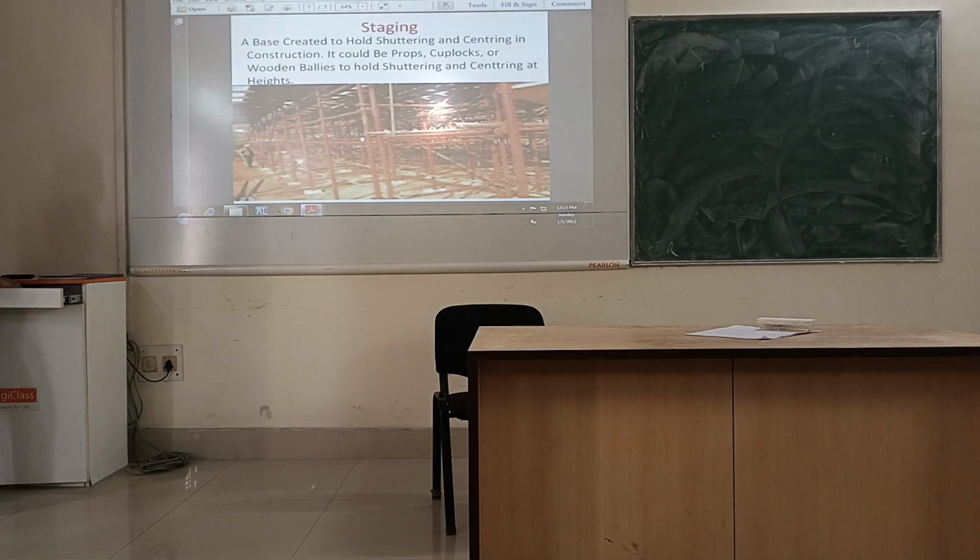Okay. Next is your staging. Staging is what? Staging is the prop that we provide to hold the load of the shuttering and centering work. Because once the centering work is done and shuttering work is done, this needs to be supported with the vertical members, props. So these are called your staging. Okay. These are the props. Top blocks are used to hold it, or even wooden battens are also used. These are used for holding the shuttering and centering and tying.